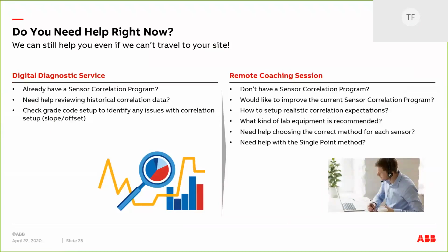That is different from the SPC rules that I see most people following. So what is your opinion versus what do you follow? Do you follow the SPC bump procedures, which I think only gets you right on the average? It does nothing about your slope or your range. Or are you using the statistical methods on the XY correlation to make the changes?